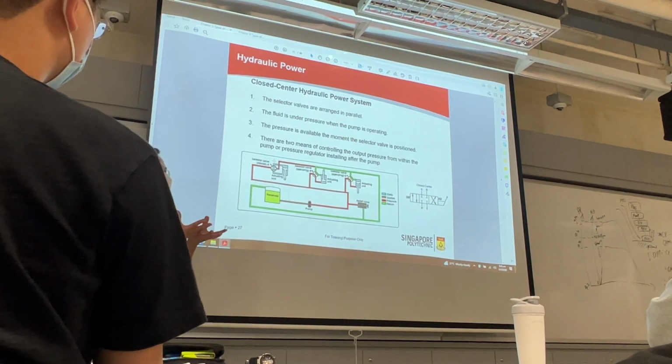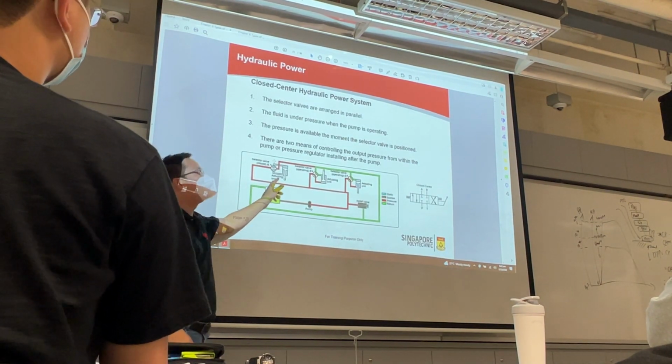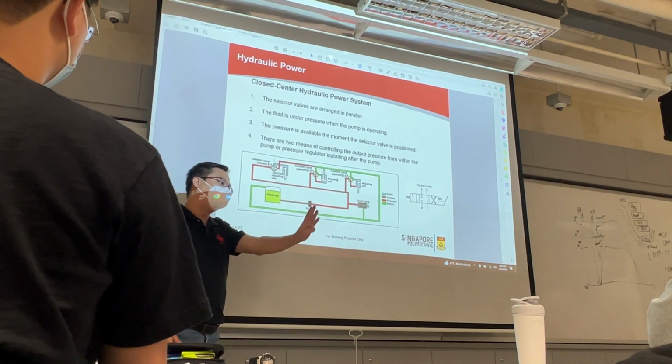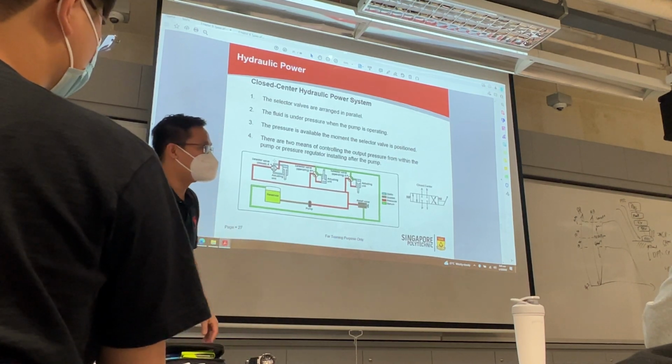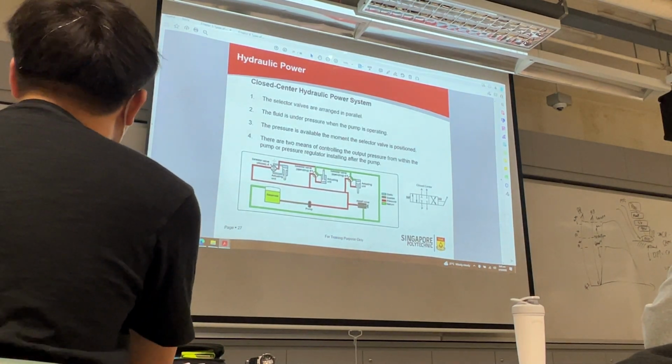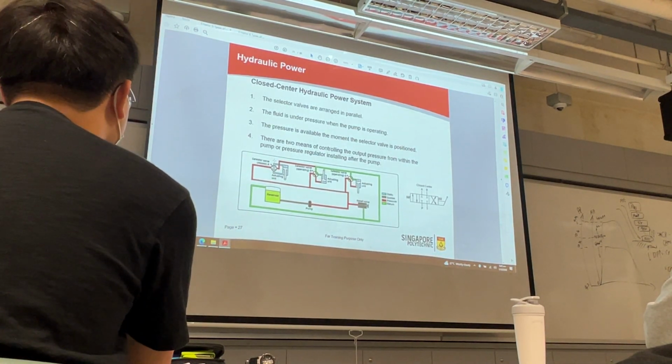They optimize it in terms of weight, and they tell you, please, landing gear first, fully retract, then do the flaps. Don't do both at the same time. Understand that? So it doesn't mean that it's unlimited. The pump is not the strongest guy.